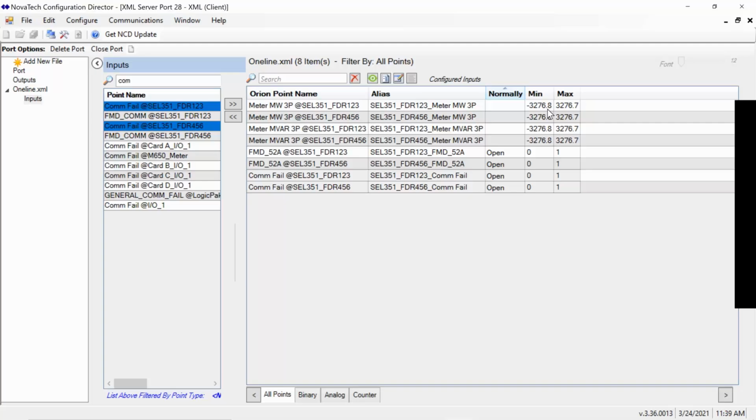Yeah, so what's typical is, and this is going to depend on the configuration and the parameters in your IED, but what we typically do is one-for-one mapping from an IED back up to a SCADA master, so that we can use the concept of preserving the decimal. DNP is only capable of transmitting integers. I like to use frequency as an example: if I had a perfect 60 hertz, typically the raw value transmitted would actually be 60,000, and that serves as an integer base, but it still has that decimal representation when that value is divided by 100 once it finally reaches its end destination, termed recovering the decimal.